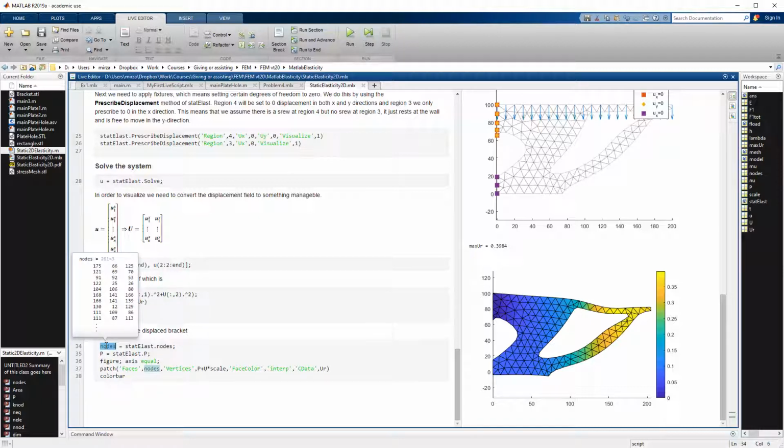So basically this means that if you read it from top to bottom here, the first element has a node 175 and 66 and 125, and these nodes are referencing these points here. So the points are referenced by these triangles. So every row here is basically one element or one triangle with 3 nodes, and the node numbers are whatever it says there.